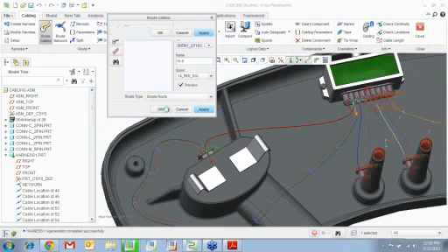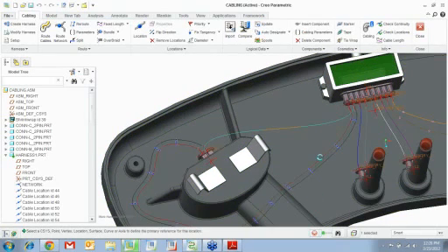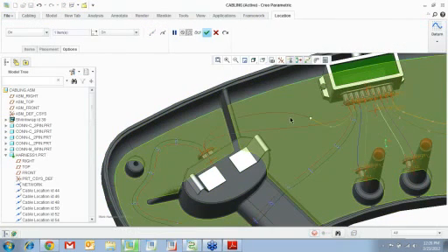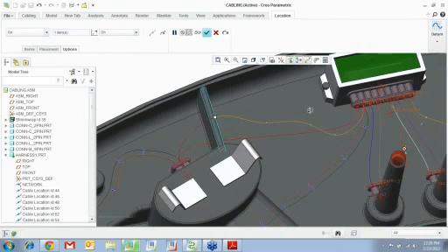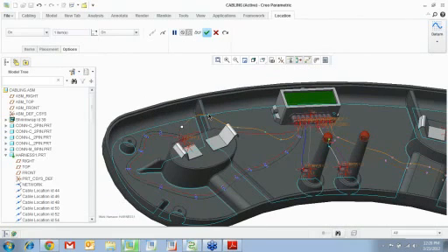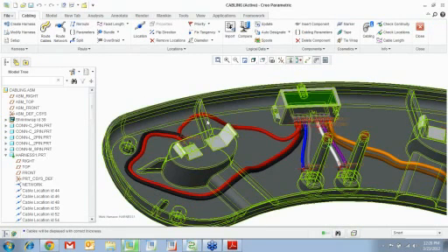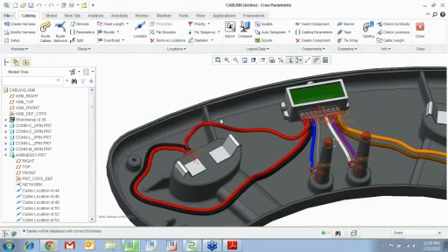See that? Say okay. You can actually then do insert location on it. So you can go 1, 2, 3, and I want to go right over there, over here, and say done. Now you can see that you just routed a wire without having any schematic. So if you want to do it manually, you'd have to do that for each and every wire and have colors, all those other details added to it.